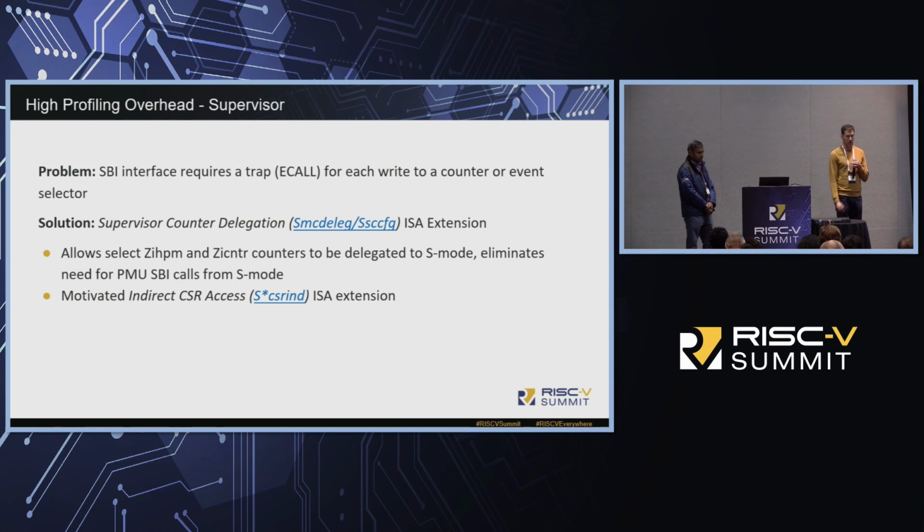So once again, we looked to the ISA to address this issue. We came up with the supervisor counter delegation ISA extension. What this does is essentially allow M mode to opt into selecting counters that can be accessed or written directly by supervisor mode.